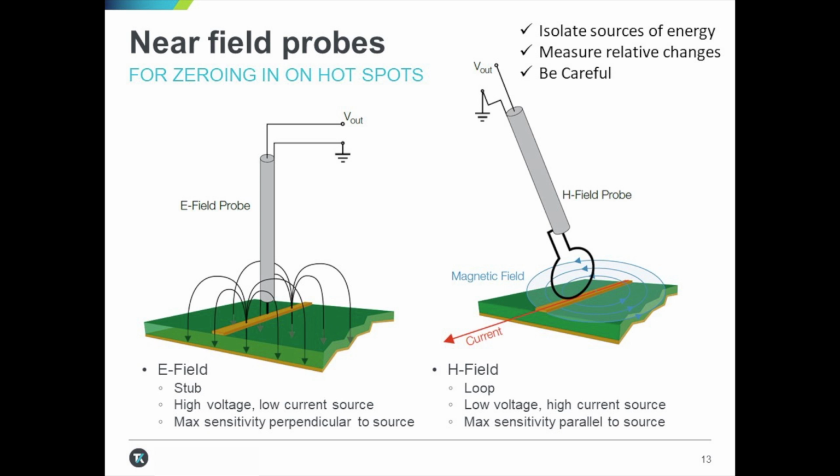In practice, E-field probes are ideally suited for zeroing in on a very small area, identifying sources with relatively high voltages as well as sources with no terminations. At low frequencies, the circuit node impedances in a system can vary greatly. Therefore, knowledge of the circuit or experimentation is required to determine whether an H-field or an E-field probe will provide the most sensitivity. At higher frequencies, these differences are dramatic.